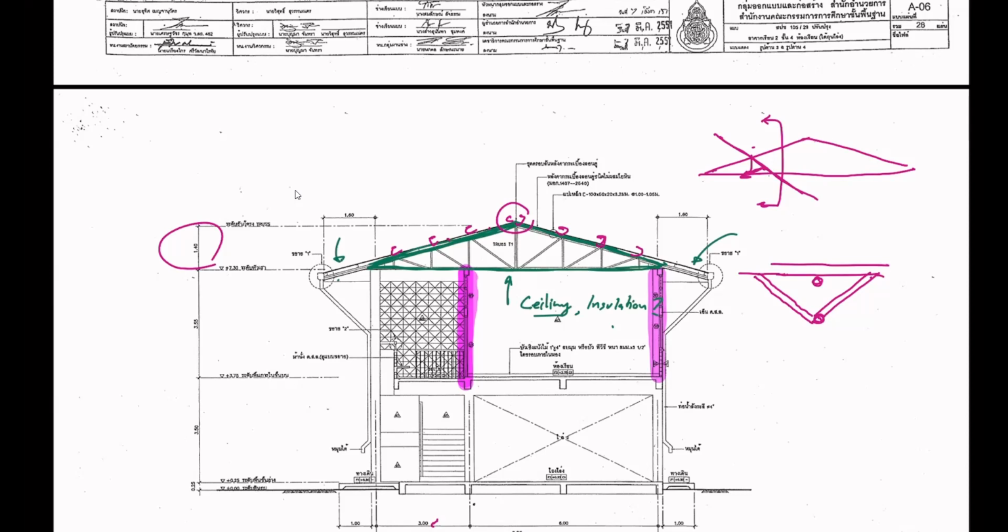In that case, you're going to have to use the roof slope as recommended by the tiles, because I told you to use the roof to your liking. So this slope may not be applicable, and you may have a better depth for your truss. That recommendation is for water drainage. If you use a slope less than that, you're going to have a ponding problem. The water will stay on the roof and leaking will occur. So if you change the tile and it requires a different slope, please stick to that, okay?